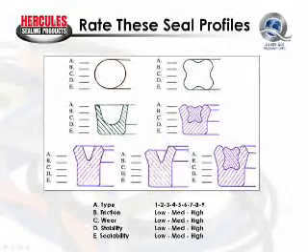Another feature of an asymmetrical seal is that it usually is designed so that the static side of the seal fits much more tightly against the static surface, cutting off a low-pressure leakage path on this side. So we're looking at probably a seal in the 7 range here. Friction is medium to high, wear is medium to high. Stability is extremely high. The sealability of this seal is going to be higher than this symmetrical seal. It's going to be very high.